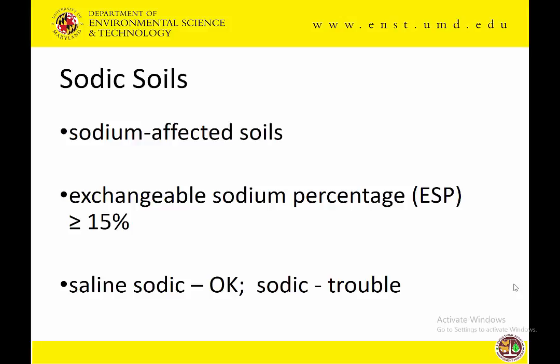They're still permeable. But sodic soils that are not saline, just sodic soils in the non-saline range, can have dispersed clays. They are extremely problematic, and they need to be reclaimed before you can grow anything in them. Because if you irrigate or there's rainfall on them, the water literally sits there until it evaporates. Right? They are not permeable.